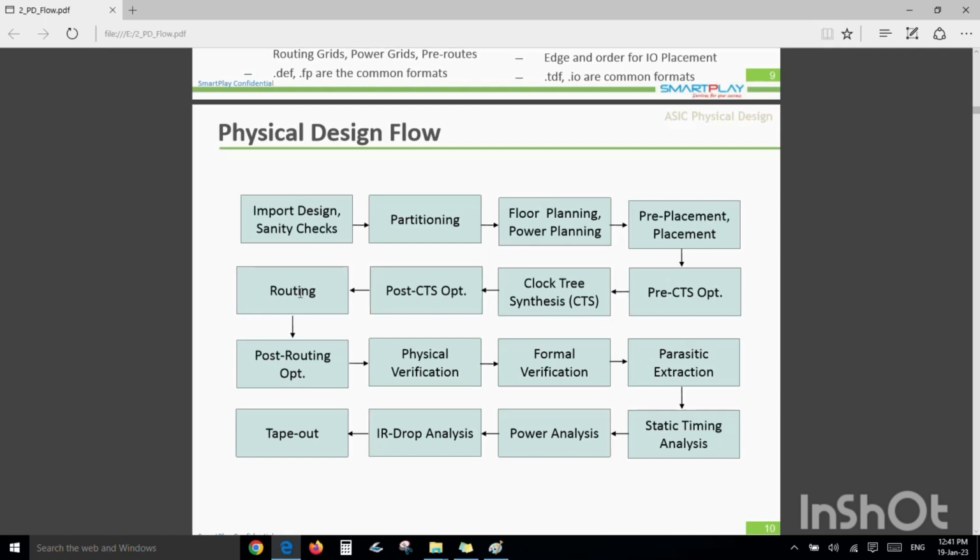After that, we are routing also, and we used to have DRC issues, LVS issues, and all these issues, and we need to fix setup time and hold time also, since actual routing is coming into the picture. So what we can do is reduce the violations as early as possible. Let us take one violation that I got in the pre-CTS stage.